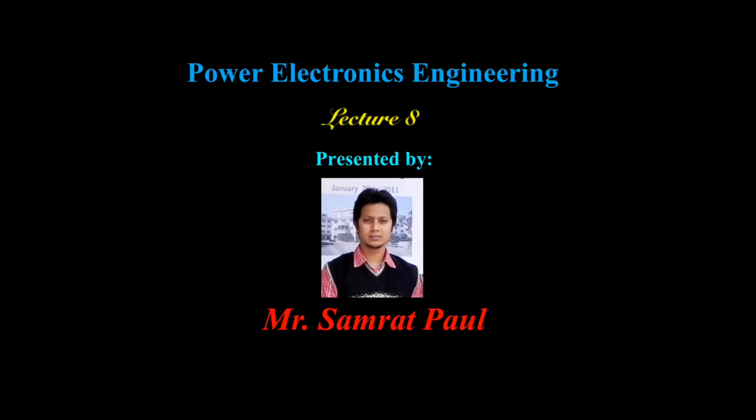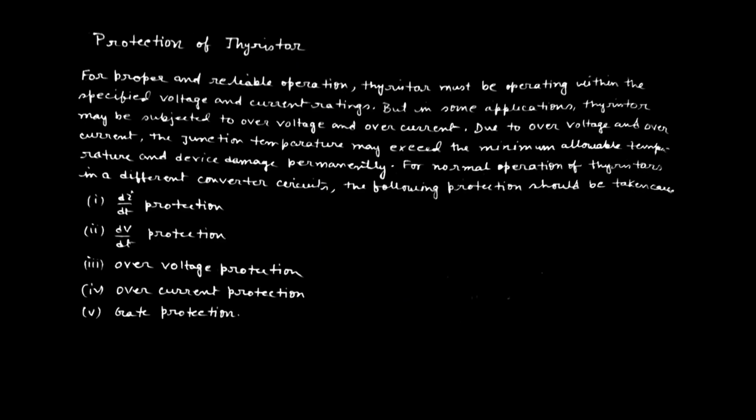For normal operation of the thyristors in different converter circuits, the following protections should be taken care of, like di/dt protection, dv/dt protection, overvoltage protection, overcurrent protection and gate protection. So the first is di/dt protection.